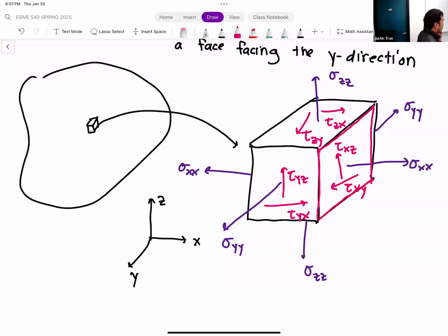Okay, good. All right, so when you're using ANSYS, and you can definitely try this out in the activity next week, you can actually ask ANSYS to show you the different components of the stress. Typically, what we display is what's called the equivalent stress, which I'll define in a second. But you can ask ANSYS to show you the normal stresses as well as the shear stresses, and you can show the different components of the normal stress and the shear stresses as well.